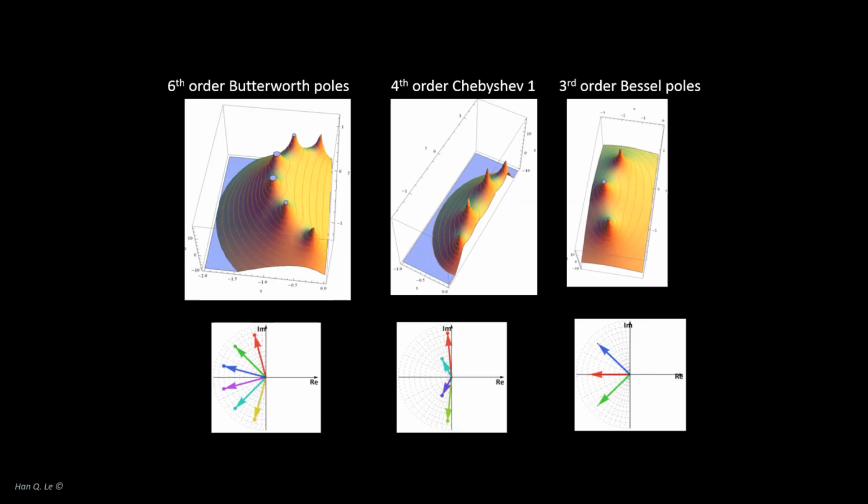How are the roots chosen? This slide is to benefit those who have taken signal analysis filter design. A filter designer can choose as many roots as needed. There are a number of root configurations as shown here. The figures are the 3D plots of the various transfer functions, where the roots appear as the poles, or the mountain peaks, in the plots.